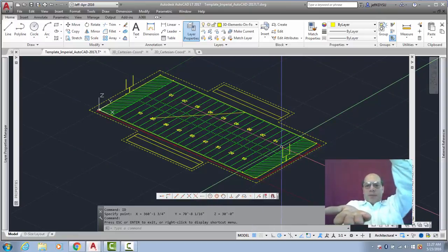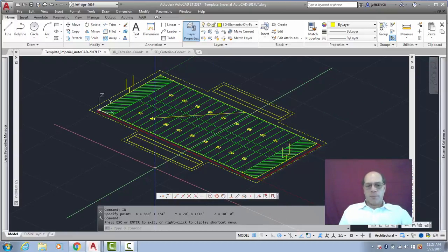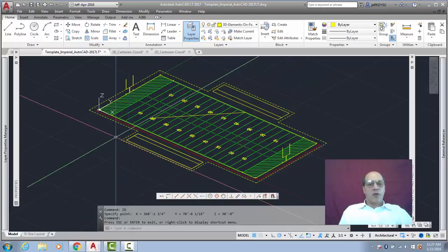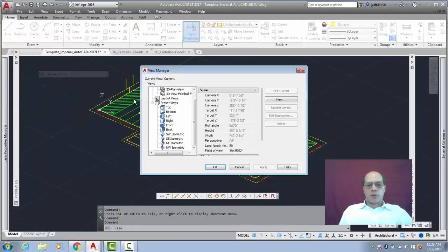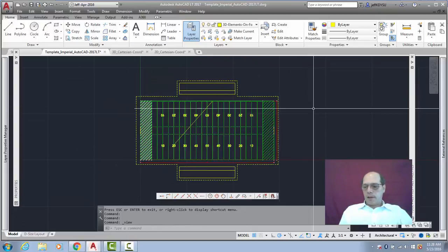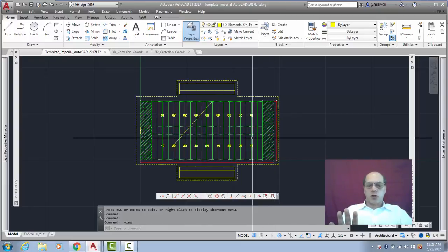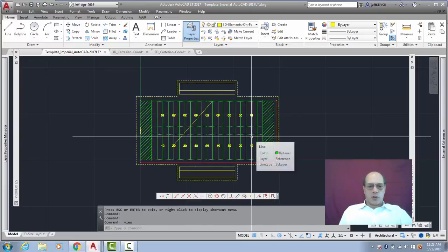So if I'm in the Goodyear blimp and I'm looking straight down on that goalpost in the football game, then you would only see a dot. So let's go up to our pull down to view, and we're going to go to our named views, and I'm going to tell this pre-made view that I want to set current my 2D view. We're now looking at that football field, and I'm seeing just a dot. The reason for that is I'm looking at a 3-dimensional object in 2D. This course will be teaching us how to do 2-dimensional drafting in AutoCAD.